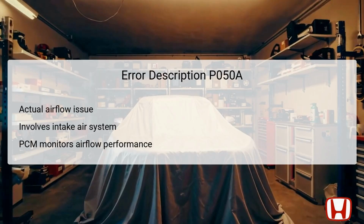The DTC P050A signifies a cold start idle air control system performance issue. At its core, it indicates that the actual airflow entering the engine during cold starts is not aligning with the targeted airflow that the PCM anticipates. This situation typically occurs during the vehicle's quick warm-up process, where airflow management is crucial for optimal engine performance. The PCM plays a vital role in ensuring the engine receives the right amount of air for combustion, and any anomaly here can lead to poor engine functioning.